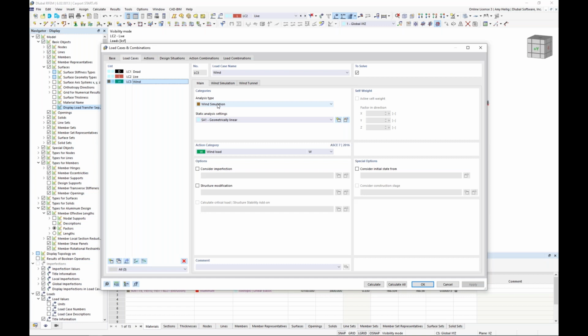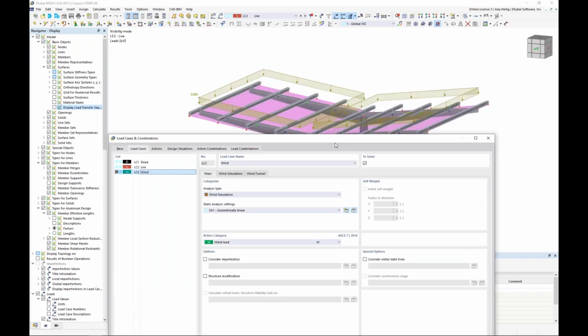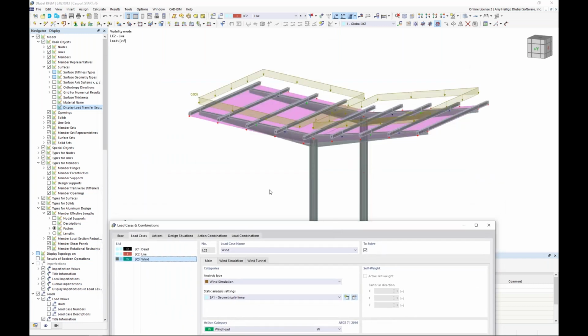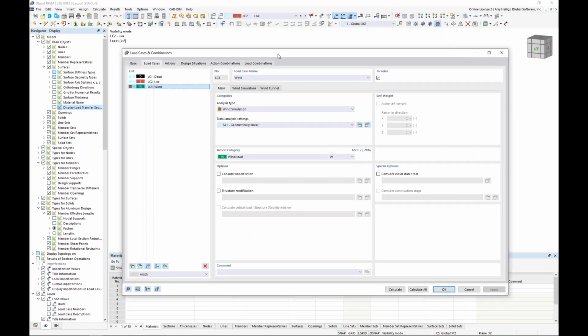So why would we want to use this? Well, when we refer to the ASCE 7 for freestanding carports or freestanding canopies, there really is no guidance in the code on minimum wind loads. We're simply supposed to treat this structure like an open building. So this could be a disadvantage in some scenarios because the minimum wind loads are much too high, or maybe they're much too low. So it might be worthwhile using RWIND, the standalone program, as just an additional tool to compare to the minimum wind loads that are set forth within the ASCE 7.